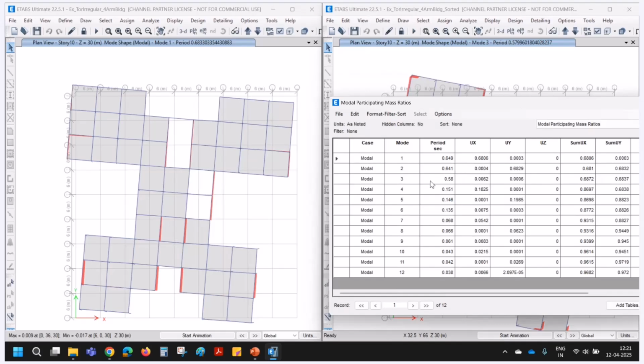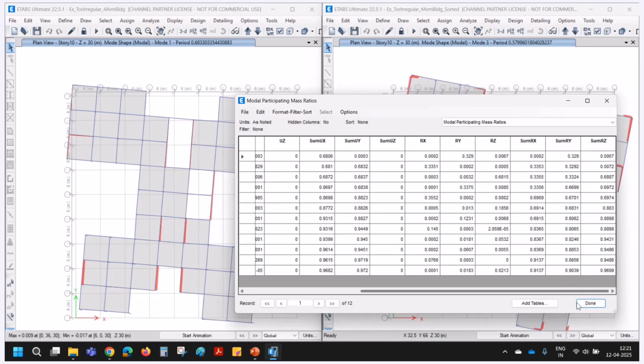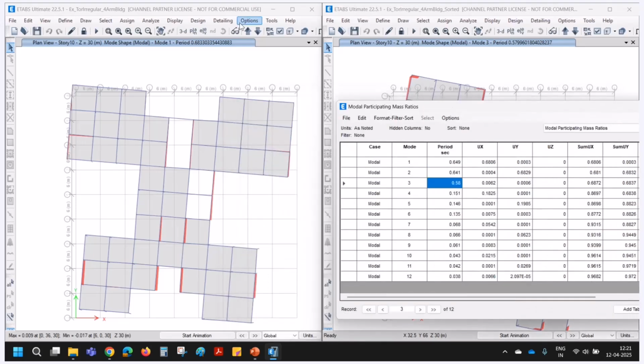Here, the torsional mode. Some coupling is expected because we cannot make it so perfect that only translation is available in the first two modes. But this is significantly away from the translation modes, mode 3, compared to this one.